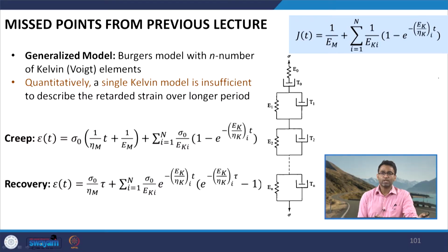So, this is actually the importance of these modeling techniques, and we have preliminarily discussed simple models here, let us say the spring and dashpot element. There are other more complicated elements, we have fractional dashpot elements, we have a combination of spring and fractional dashpot elements. So, there are several other models which exist, and you may definitely look at them if you are interested. The main purpose of this lecture was to describe in a simple way how the viscoelastic behavior of bitumen can be expected to be, alright.